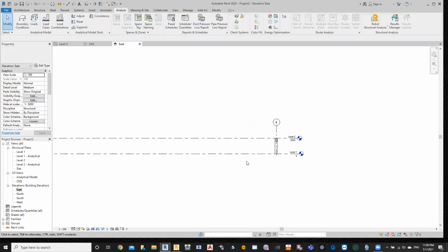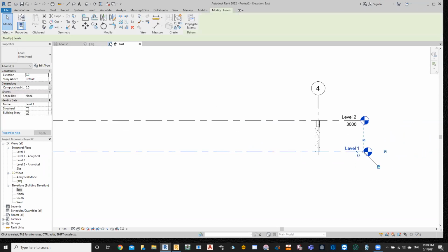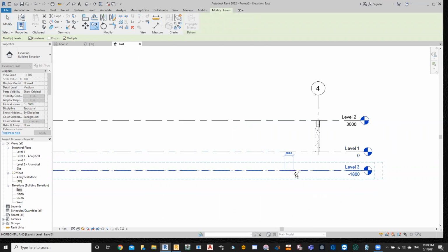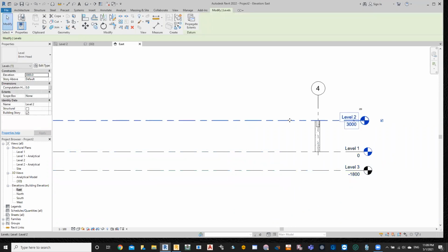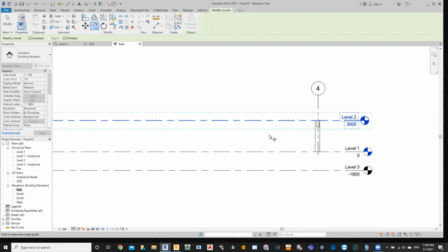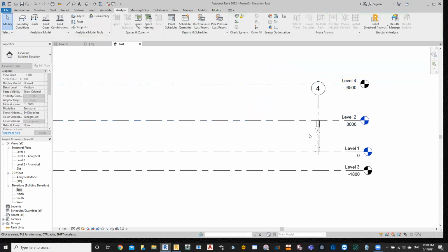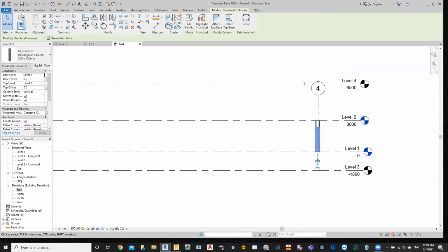You can copy the level. So for example, I have another level here, 1,800, and I have another level here. Of course, you don't need to go for the copy. You can enter once again, so it will give you the previous function. Highlighted, for example, going 3,500. Now you can copy according to whatever levels are there.